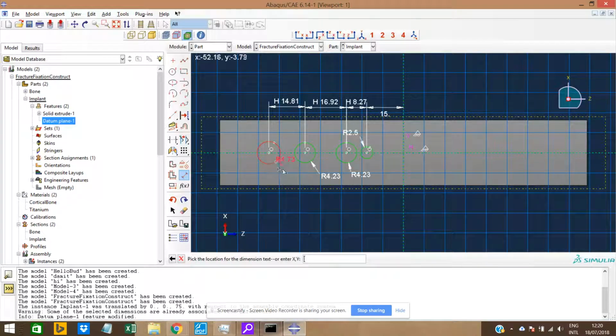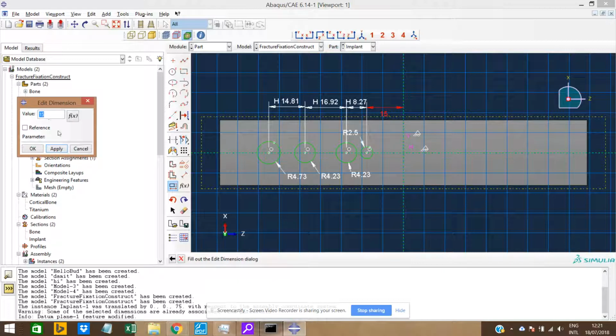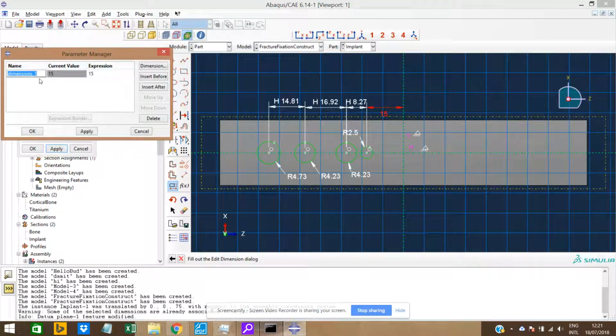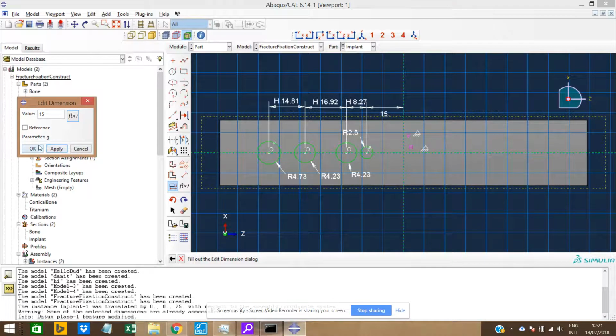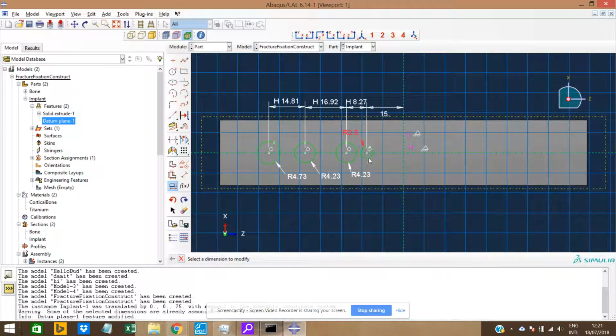The one thing this one is nice for is if you want to skip all the trial and error that I did before, you just look at this one, because since I did it before, I guess I'm a little bit faster. Anyway, so I go and I click on you, and I'm gonna call you again. This time I call you G. By the way, if you want to move things around, you always use this little thing in SolidWorks.